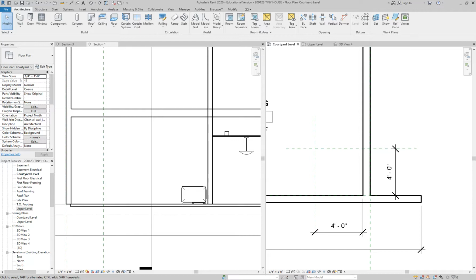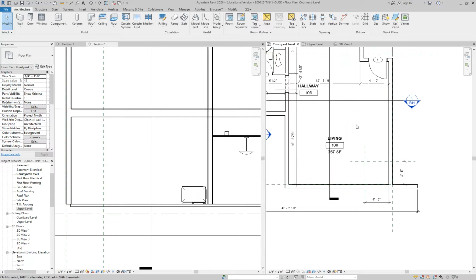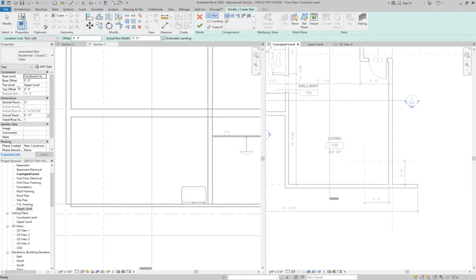Bobby, are you able to create stairs going down rather than up? Yeah, you can. Is it the opposite direction? Yep. What you would do is specify the base level. If you were on your second level, Revit will already see that we have to go down. But if we were on our first level and we had a basement, it might not know. So when we start our stairs, just like our walls, we've got our base level and then our top level, and sometimes you can flip that around. Really similar to walls.